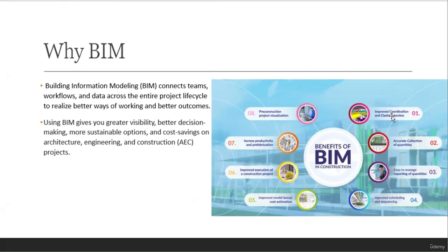BIM not only helps us in clash detection, but it has its own variety of uses. Like it can help in calculating the bill of material of a project, that is model-based quantification. Assigning cost parameter to these quantifications helps us in getting the overall cost of the project in one go. Scheduling and sequencing using BIM can help us to have much greater clarity compared to the conventional way. We can plan site activities, decide on material procurement efficiently using BIM. So this overall helps us in improvised execution of a construction project and therein leading to cost saving and time saving. Okay.